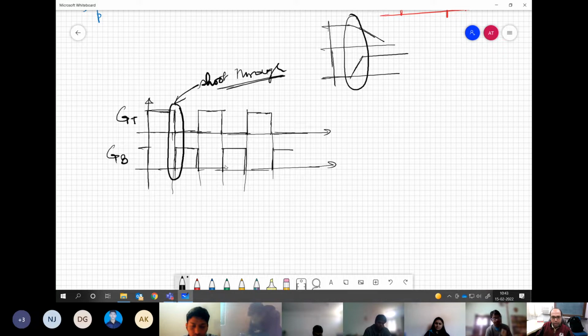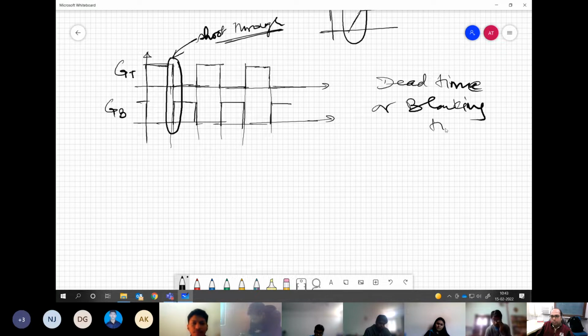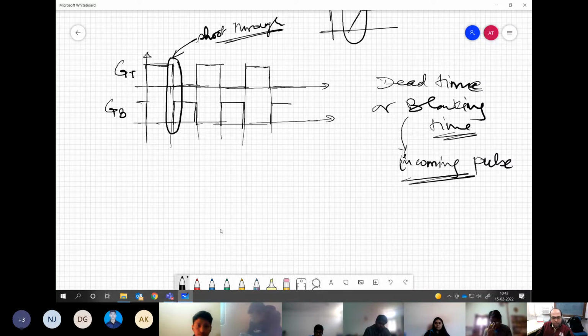So what we do, we introduce something called dead time or blanking time, for the incoming pulse. This is only done for the incoming pulse. We do not disturb the outgoing pulse, which means that we will not touch this edge, but we will modify this.